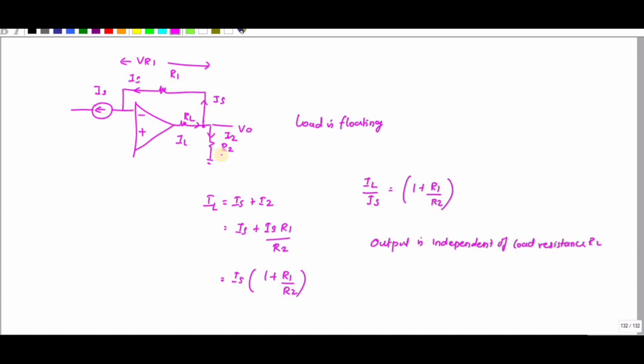So the op-amp output voltage has to be more positive than VR2. While designing, the sum of the voltage drops across RL and R2 must not be so large that the op-amp output attempts to exceed its maximum output voltage range.